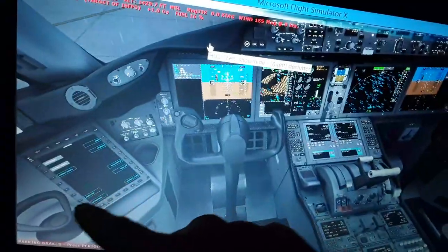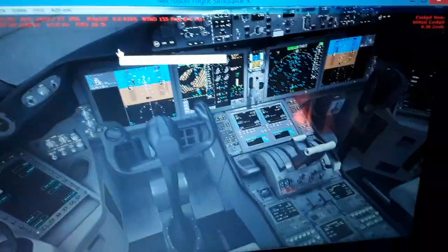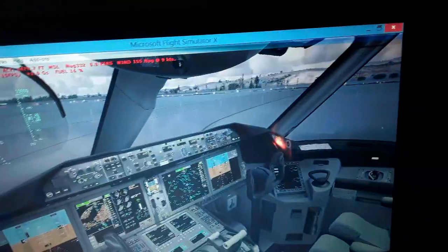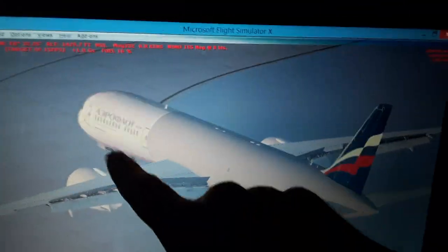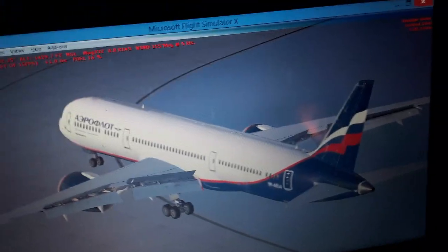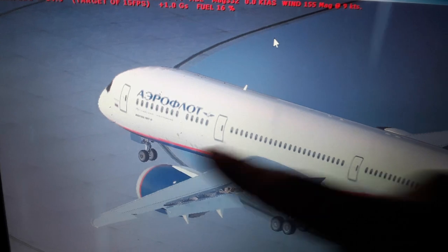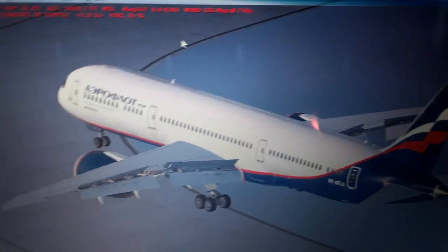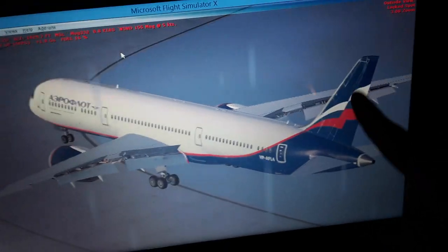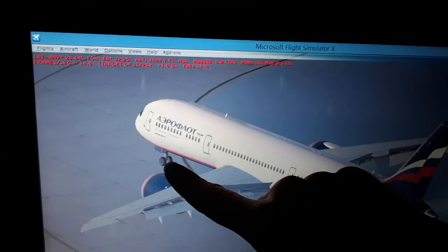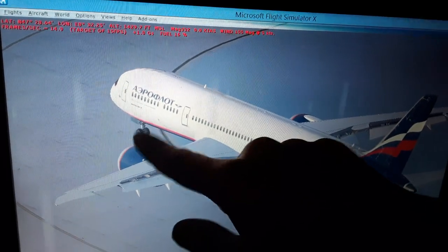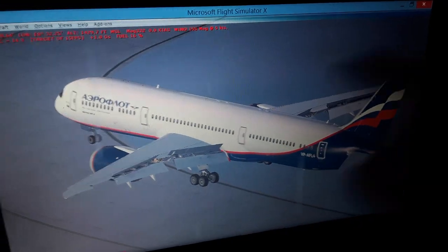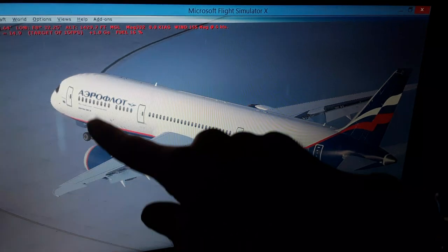Also we have the tiller, the nose wheel steering. So the nose wheel is interconnected with the rudder in the ground, so you can use the wheels, the forward wheels, as you can see here, the forward wheels of the aircraft that deflect either 76 degrees left and right from 0 knots airspeed all the way up to 45 knots. In 45 knots we have the rudder aerodynamically effective at takeoff or at landing. So the nose wheel decreases in deflection from 76 to like 7.6 maximum, and then all the way up to like 70 or 80 knots in takeoff, like 200 kilometers an hour.